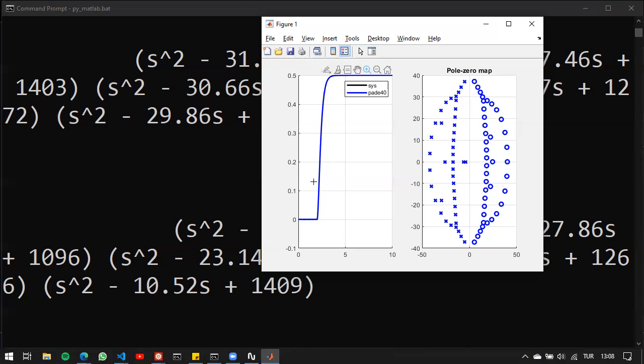So therefore, you should pick the least possible order, maybe the first order one, design a controller, apply it to the system and see if it works. If not, increase the order, let's say 2, and try it again. And if that's again not sufficient, increase one order more, 3, 4. So there's this iteration going on. You should start with 1, and at some point, if you're happy with the controller and the behavior of the closed loop, then you're good to go.